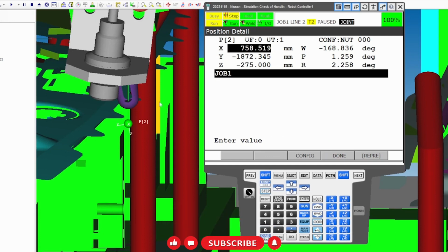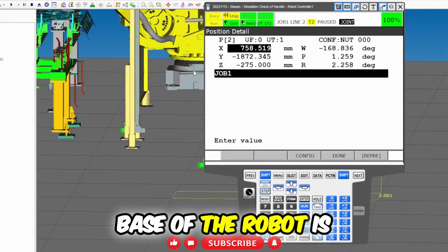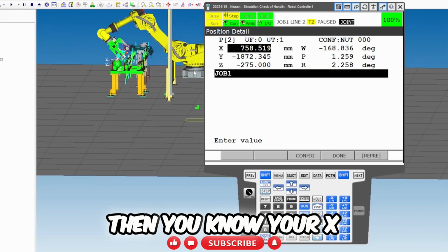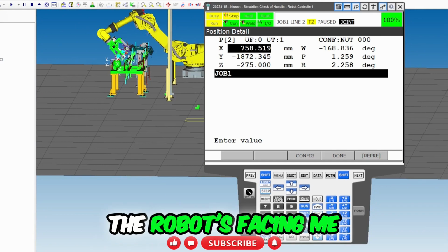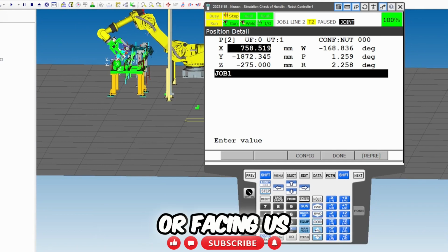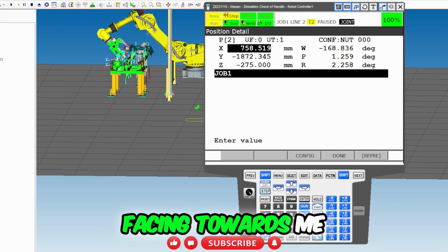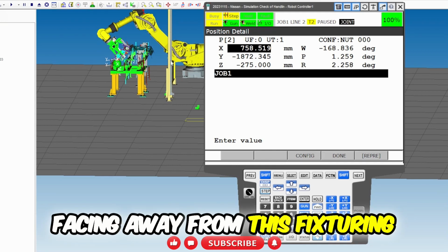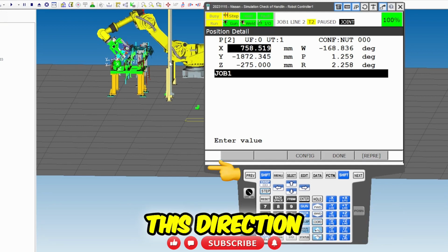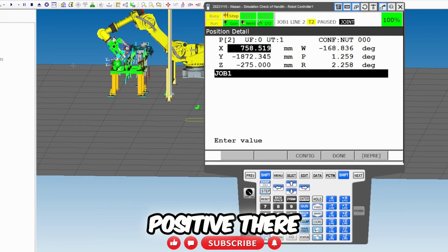And then I need to zoom out from the robot to see where the base of the robot is. Once you know the base of the robot, then you know your X, Y, Z, if this is in world frame. If we're in world frame, the robot's facing me, or facing us, however you're looking at this, which means X is facing towards me, and Y is facing away from this fixturing. So Y positive is this direction, X is this direction, and then obviously Z positive there.